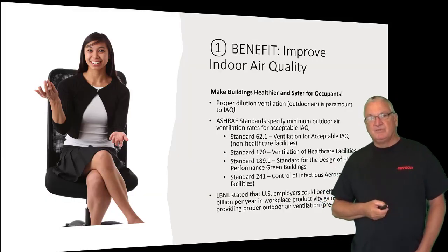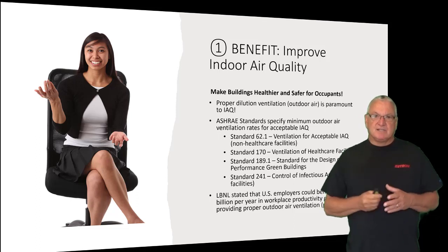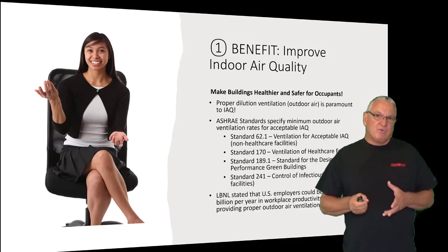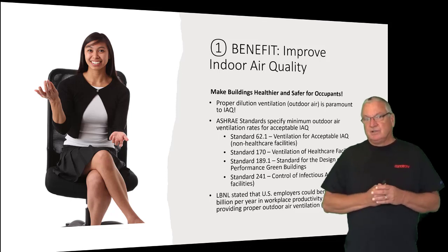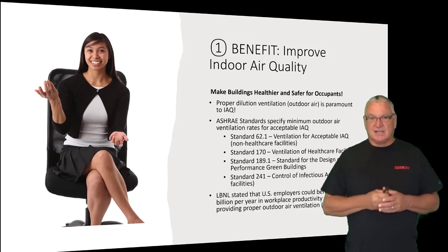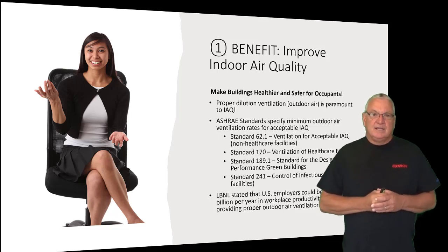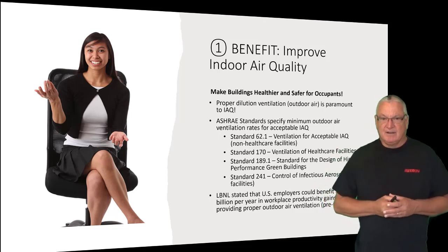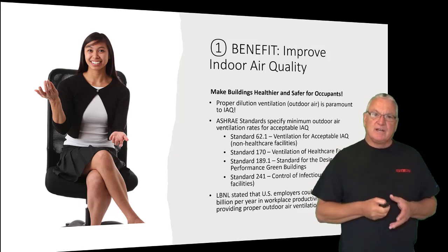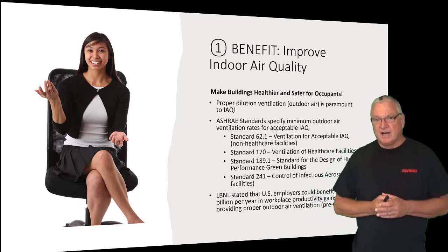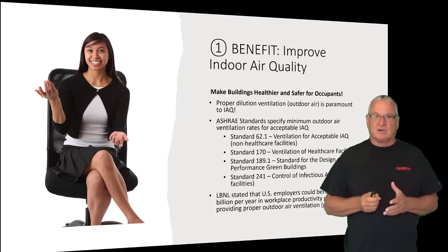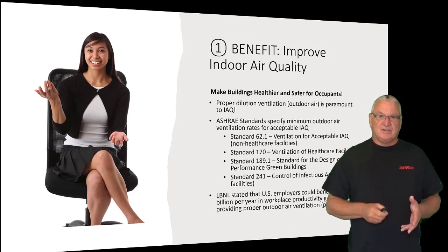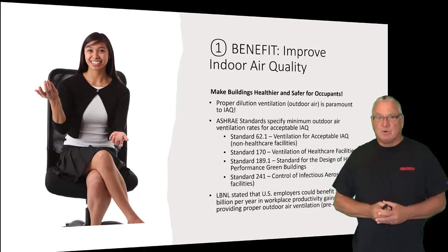When we talk about the benefit of improving indoor air quality, we've got some really nice presentations on this, but basically what we want is for everybody to understand that a prerequisite to acceptable indoor air quality is proper dilution outdoor air. It's also combined with filtration, and in some cases, depending on what's going on, we may add other things to, if there's viruses, kill the virus, and so on. But for the most part, for general indoor air quality, we're talking about outdoor air for dilution and filtration. Our expertise is outdoor airflow measurement, so that's what we'll focus on.